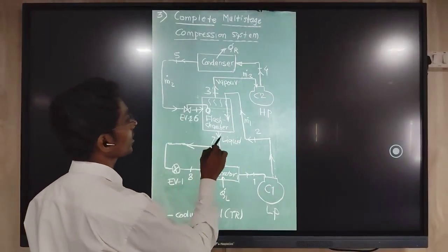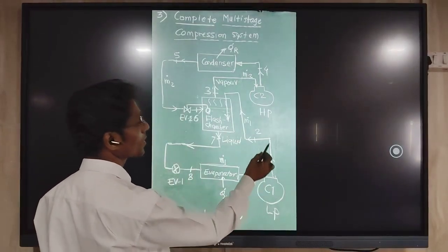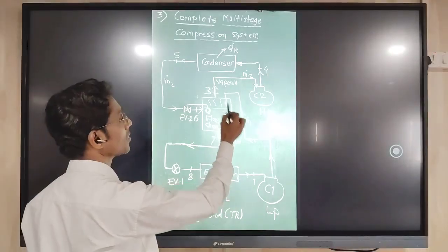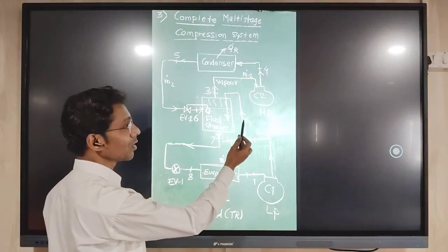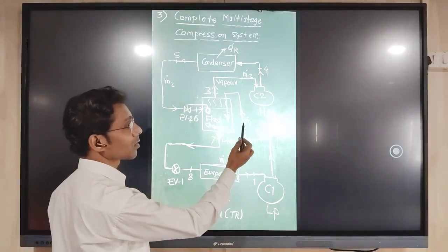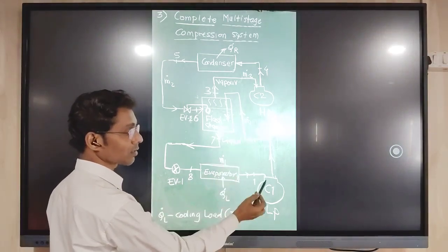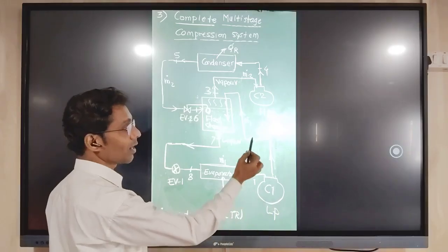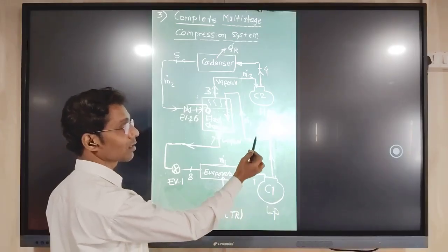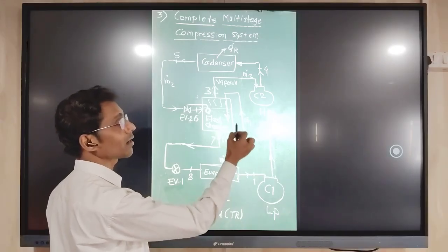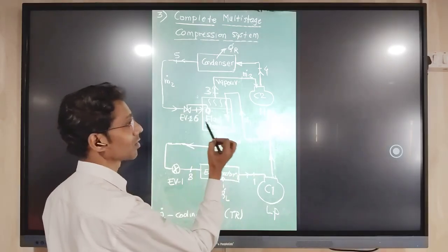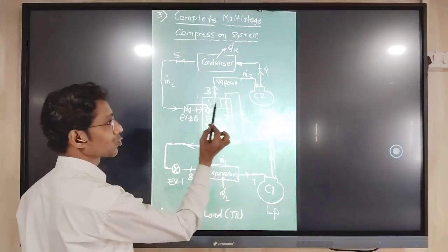So here, the entering line from compressor 1 is this entry line. To find the heat content, we take the product of the corresponding mass flow rate M1 dot of compressor 1 and the compressor exit enthalpy H2. So M1 dot H2 will be the heat content entering the flash chamber.